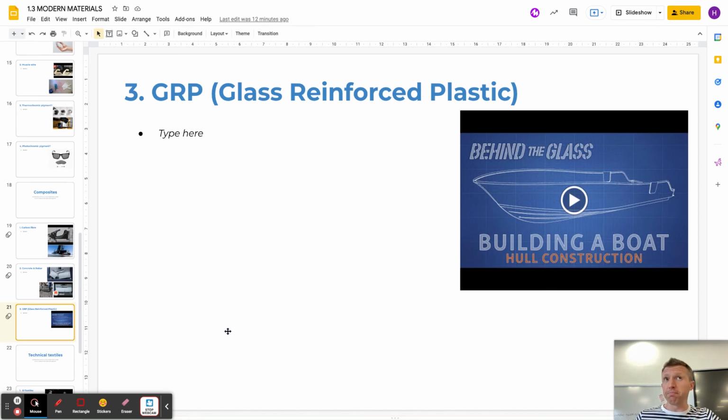And that, guys, is basically it. The important thing to know with composites is that, first, they're generally bad for the environment because they can't be separated into their constituent materials. It's a chemical reaction which bonds them together, or it's literally melting them, then they set around the other material. Number two is the repairability is very low. And number three, they're quite expensive because it takes so long to manufacture them, and so they're not suitable for mass production. They're only good for batch or one-off production. That's basically it.